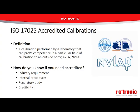Next topic we're going to discuss is accredited calibrations. And Michael will share what they are and if you need one or not. Michael? Thanks, Bruce. So if we're sending a unit out for calibration to a lab, quite often we'll have the choice between the lab's regular offering, or they might have an accredited offering. And it brings up the question, what is an accredited calibration and why would we want it? So accreditation, and typically we see accreditation to ISO 17025 when we're talking about calibration.